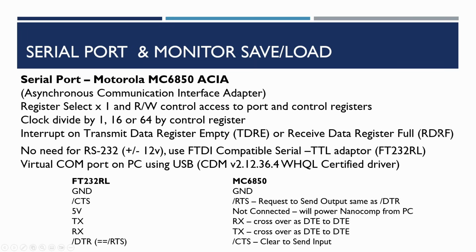If we were writing software that was going to go off and do lots of other things at the same time, we would probably want to use interrupts. But because our send and receive functions in the monitor are only doing this and not doing anything else, we can just poll these registers for the values until such time there's something to do. So as I said, there's no need for our RS232 signals, the plus or minus 12 volts, and